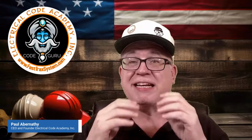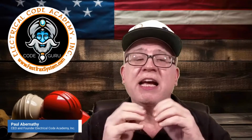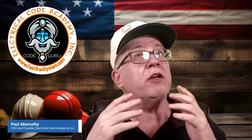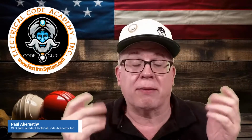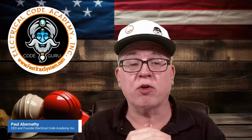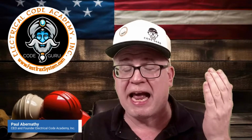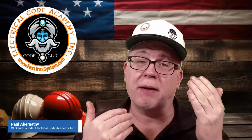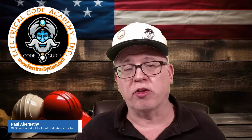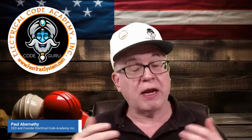summation value. So in other words, if I didn't put it on a 2-pole breaker, or on 2 single pole breakers with an identified handle tie, and I just randomly placed them in the panel, if I accidentally, or I don't know what I'm doing when I'm doing the installation, and I put it on the same phase A, let's say, or leg 1 or leg A, however you want to call it, then what happens, it becomes summation. So if I'm pulling 8 amps on the black and 8 amps on the red, and I install it improperly, then what I could get is upwards of 18 amps traveling on the neutral. Well, remember, this was, let's say, a 14-2, it's good for 15 amps. Well, I got a problem.